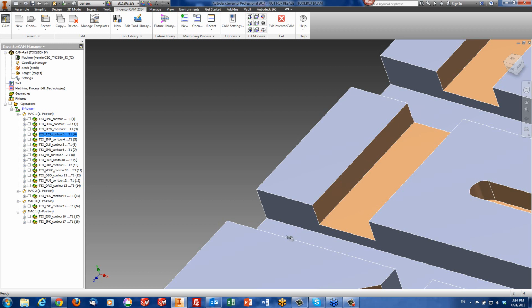Now, if you use the regular profile operations, in order to keep it down like that the way you want, what you normally would do is create a sketch along here, which would make a sketch that goes from here, another line going here, and one back. And this line would be further back in here in order to keep the tool exactly on the tool path that you want. Of course, this takes time because you have to create that sketch itself.